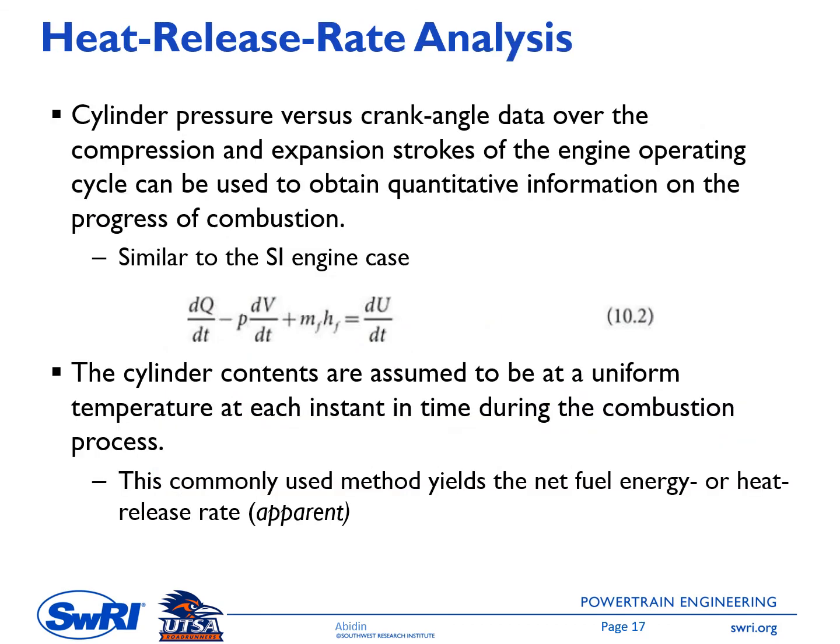So let's take a look now at the heat release rate analysis. Similar to the one in the spark ignition engine, usually we can get test data of the cylinder pressure, and then we can apply the first law of thermodynamics and the conservation of mass to get the heat release rate based on the cylinder pressure test data.